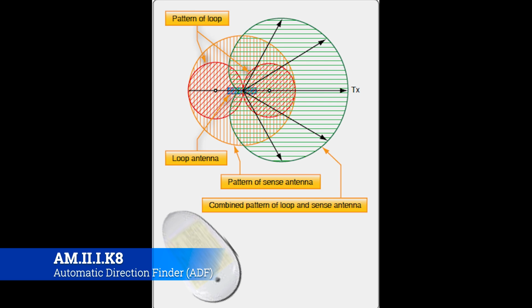You should see a slightly less strong signal, since it's a little bit further away from the station, and it should have hit at a different angle, and that angle will then allow the ADF to project exactly where the station's at. And if it knows where the station's at, then it's just simple math to say, okay, well, where am I at? You just reverse azimuth it, and that's what goes on to the card in the cockpit that lets the pilot know, hey, it's 9 degrees to our left, or whatever, bearing 1/8. So that is ADFs and how they work.